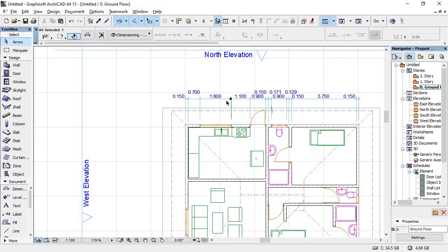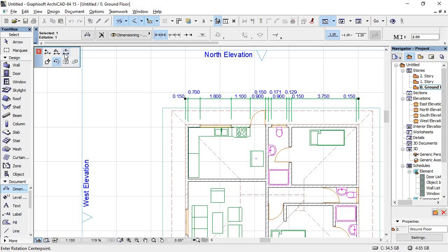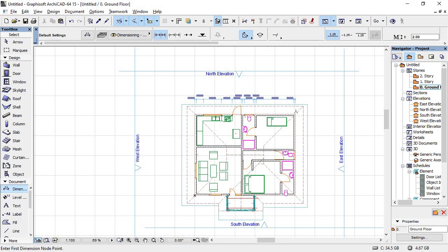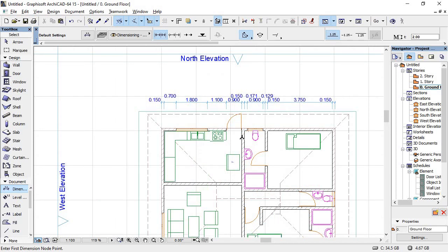After selecting the dimensioning, you can just click dimension and just click that and say you want to reduce or to edit the witness line up to that point, and repeat that with other dimensioning. You click different locations until you are able to come up with a dimensioning like this.